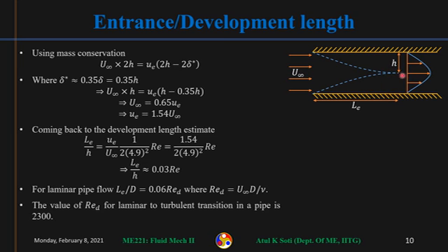We can remove this boundary layer profile, and what we can say is we shift this plate by the distance of delta star and then use the constant flow approximation, or the inviscid flow approximation. This plate will be shifted by delta star and this plate also needs to be shifted by delta star, and then in that region the inviscid flow velocity will give us the flow rate. That flow rate will be the same as the flow rate you get from integrating within the boundary layer, right?